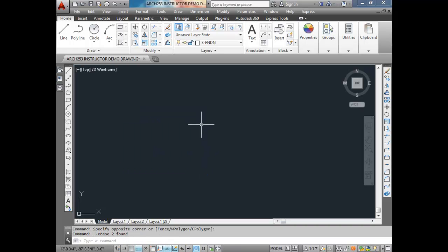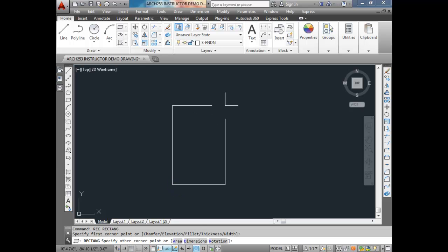So if you have your units to scale inserted content set at inches, anything you draw in inches, you don't need to worry about that little symbol anymore. Because I'm going to draw my rectangle for my plan, hang on a second here, rectangle, and I want it to be in feet, I will have to include the units for feet.